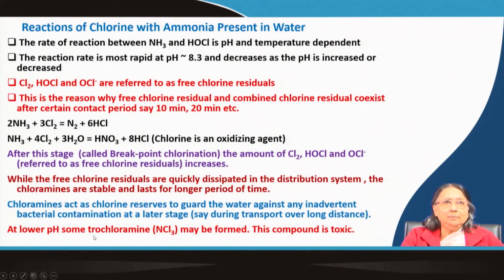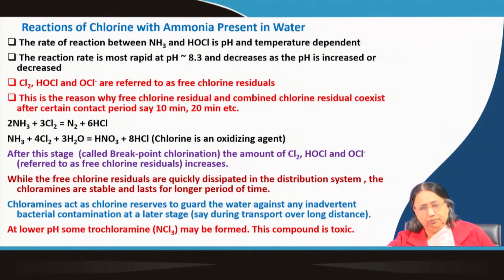At lower pH, some trichloramines may be formed, and this compound is toxic. So, during disinfection, we should not allow it to be formed. We should maintain the conditions in such a way that these things are not formed.